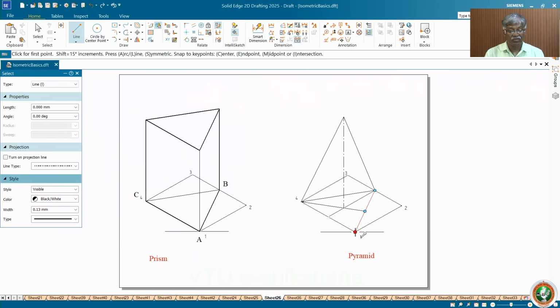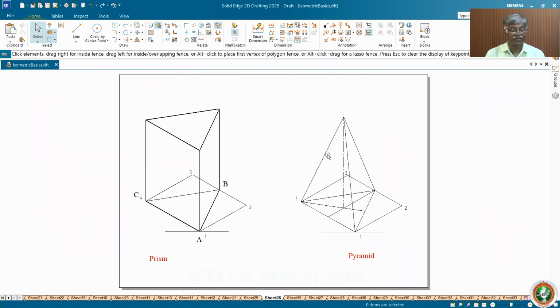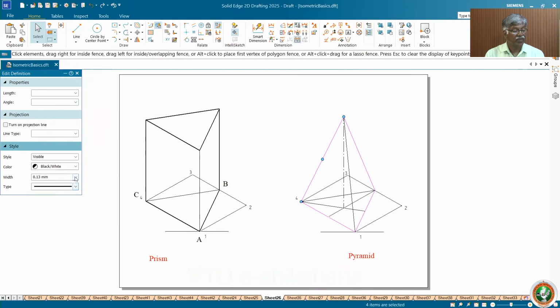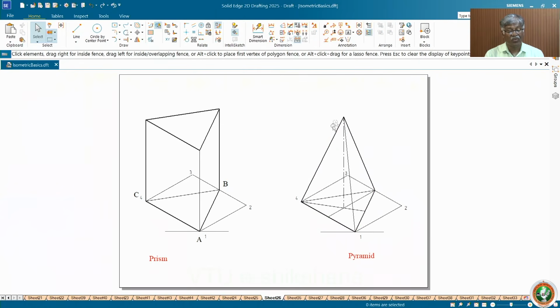So, yes. Then visibility: boundary lines dark because the base is not visible. All boundary lines, you select and make them dark. Manage the normal line, that is continuous line, visible line, and 0.5 in your case. Boundary lines dark.